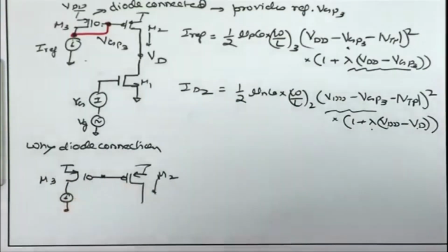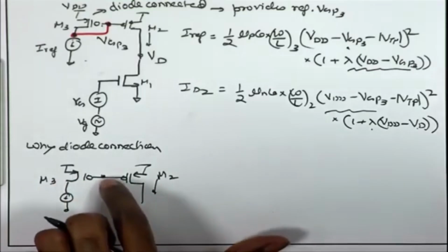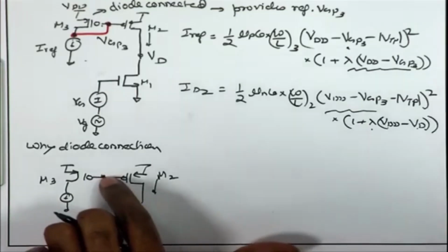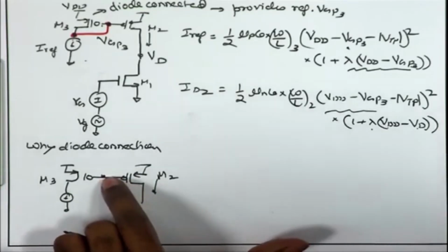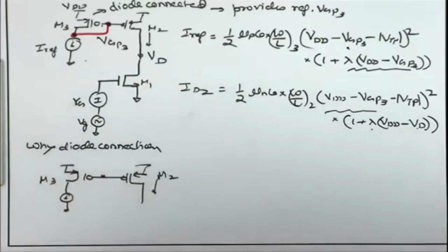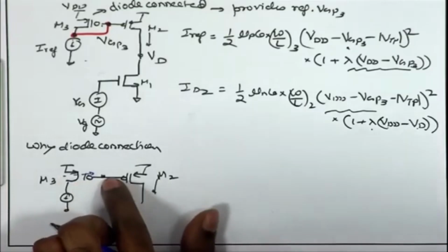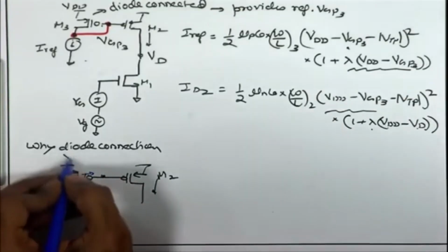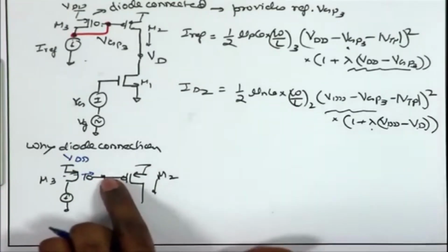So, in general, in an integrated circuit or even in discrete MOSFETs, if you do not have a direct DC connection for any circuit node or high impedance circuit load like the gate, we say it is a floating node. In this case, the gate terminal of these two MOSFETs is a floating node. We do not know what is the DC voltage over here. As a result, this can take any random value between VDD and ground depending upon some spurious current paths or the leakage current that is flowing through the MOSFET. Ideally, the oxide should not conduct, but there is some leakage path. As a result, any voltage between VDD and ground can appear over here. We do not have control on this voltage, and as a result, we do not have control on VG.